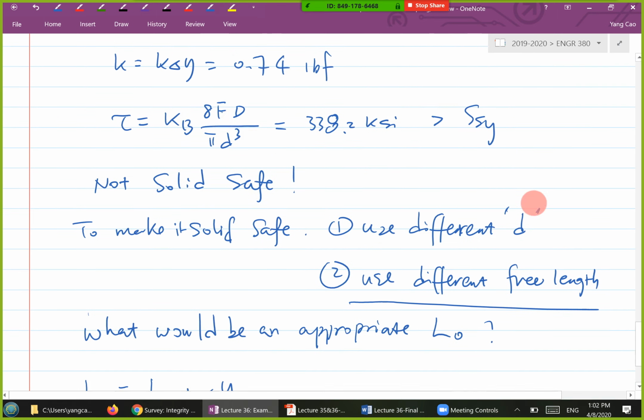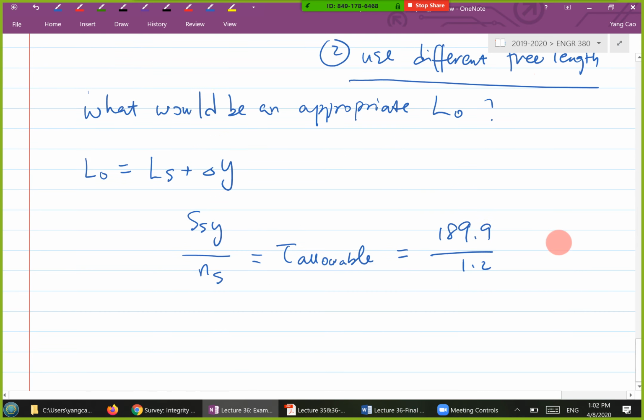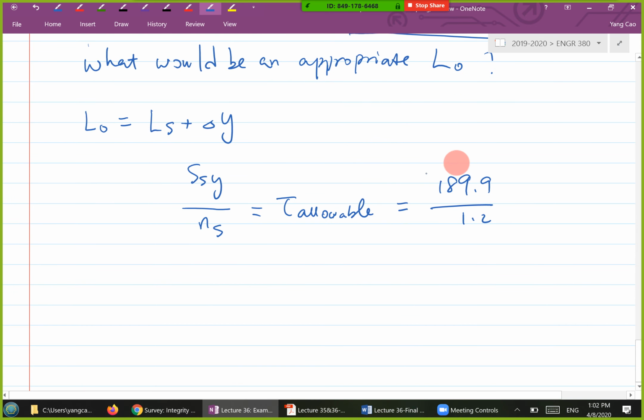Your shear stress formula, right, is given by this formula, and F here is K times delta Y. So your maximum allowable value should be the maximum value for the shear stress, which is 8 times F, but instead of F I'll replace that with K times, instead of delta Y, let's call it delta YS. So this will be the desired deflection, right?